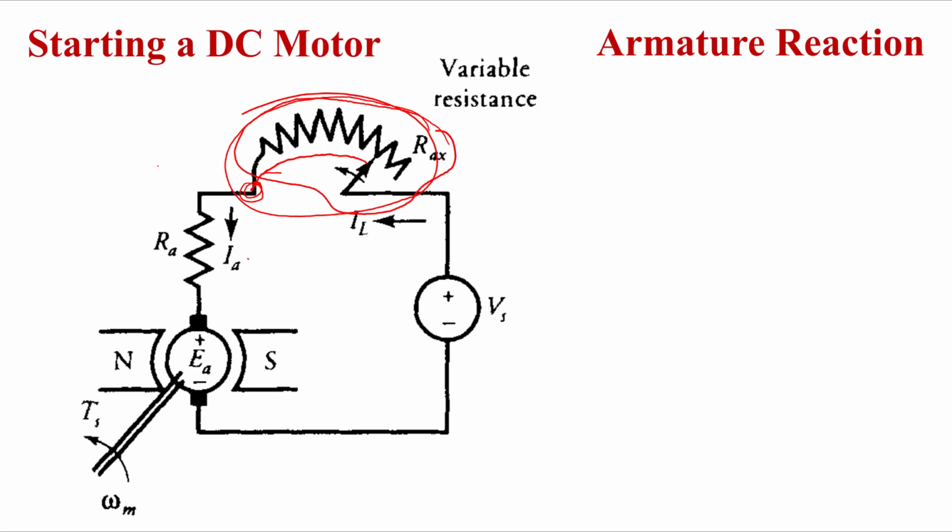The field generated due to the armature coil will be just reversed. There will be no other changes, right? Like we are putting the interpoles and compensating windings, those will remain as they are. We need not change them because they both are connected in series with the armature circuit, right? The interpoles and the compensating windings we have studied earlier also. The two things we need for the compensation of armature reaction: one is your interpole, right? And the other one is your compensating windings, right?